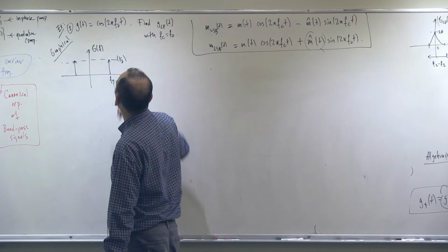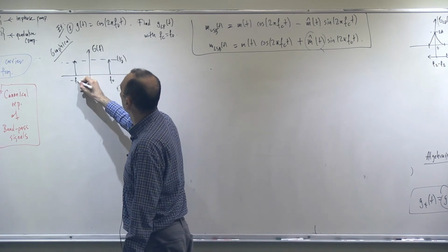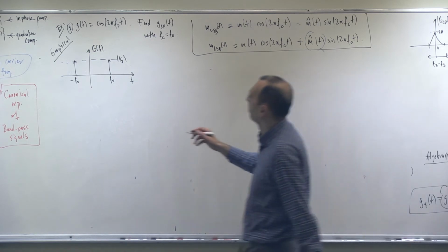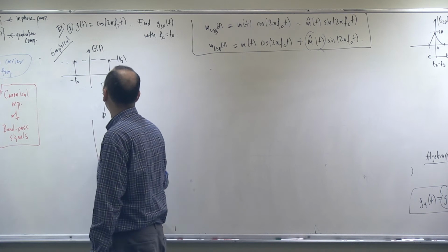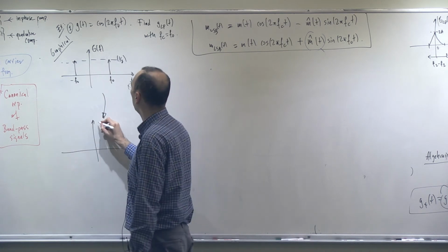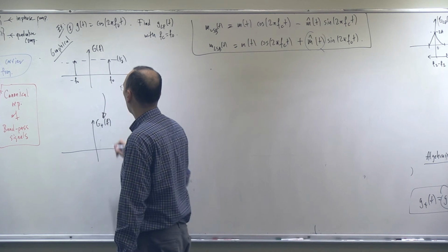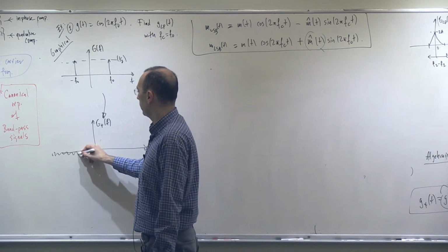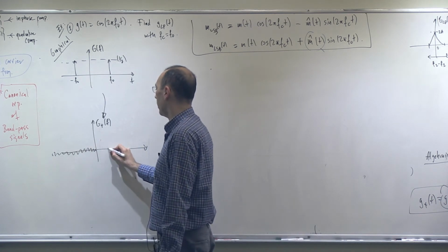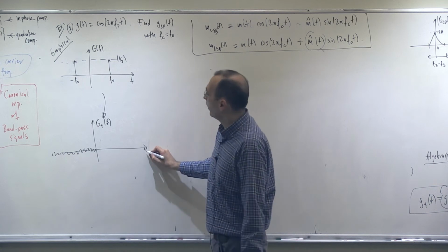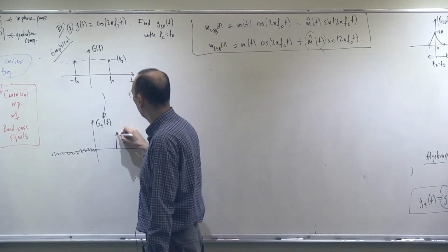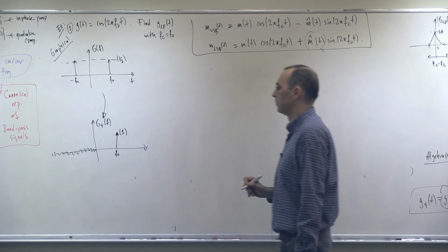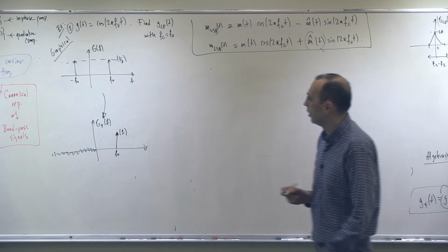Two impulses in the spectrum, am I right? Because of this cosine. Okay, what is the next step? The next step is, let me do it this way. Now you say that I'll be finding the analytic signal spectrum. So what is the analytic signal spectrum? This part is nulled. Whatever I have over here, positive frequencies, will be multiplied by 2. But since there is only this, F naught, this is the analytic signal.